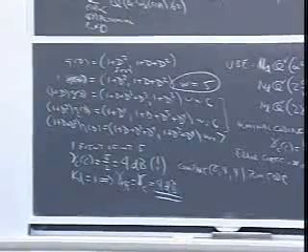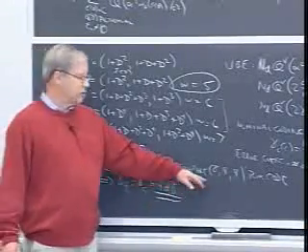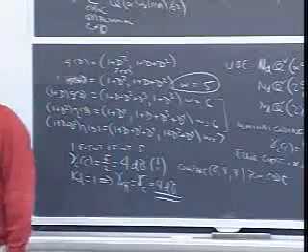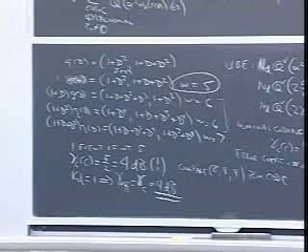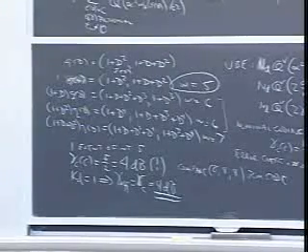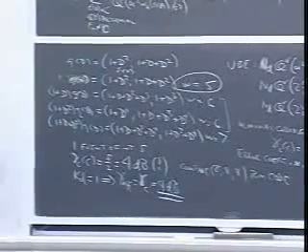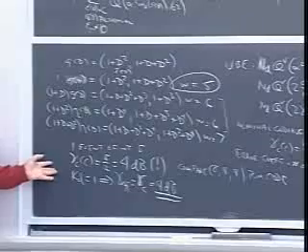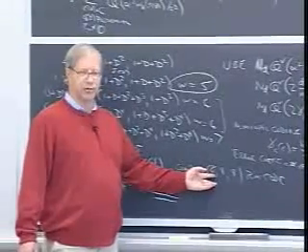All right, so this code has much better performance for about the same complexity as this code at the same rate. All right, and this tends to be typical. Convolutional codes just beat block codes when you compare them in this way. Notice that we're assuming maximum likelihood decoding. All right, we don't yet have a maximum likelihood decoding algorithm for this code.